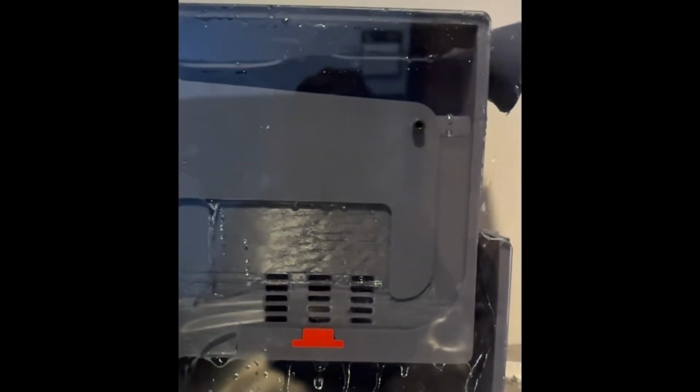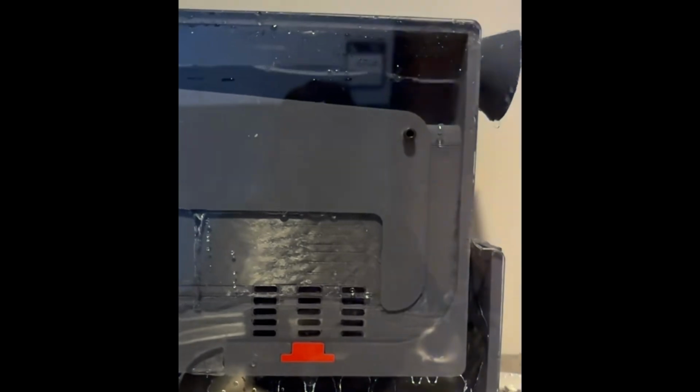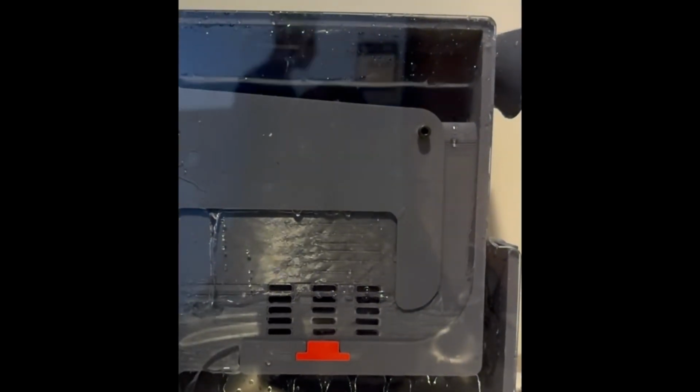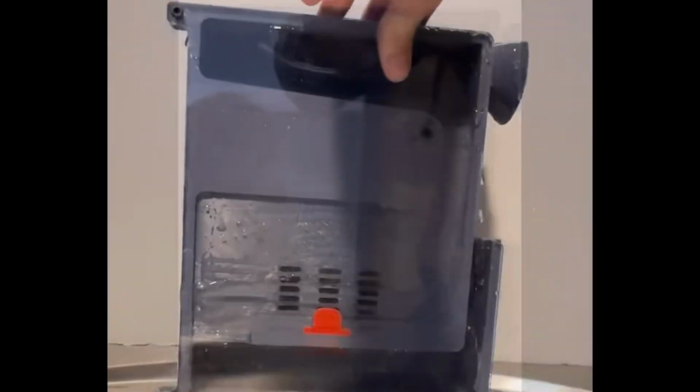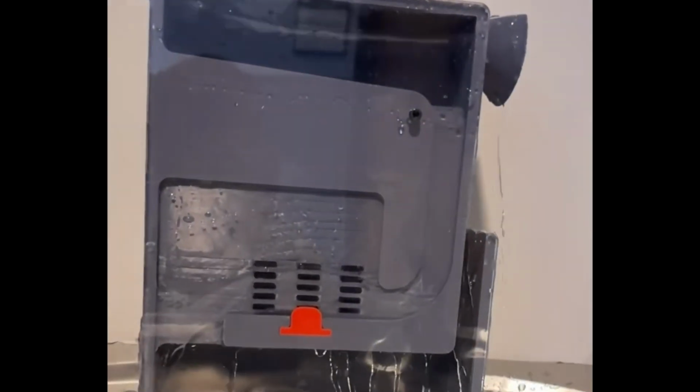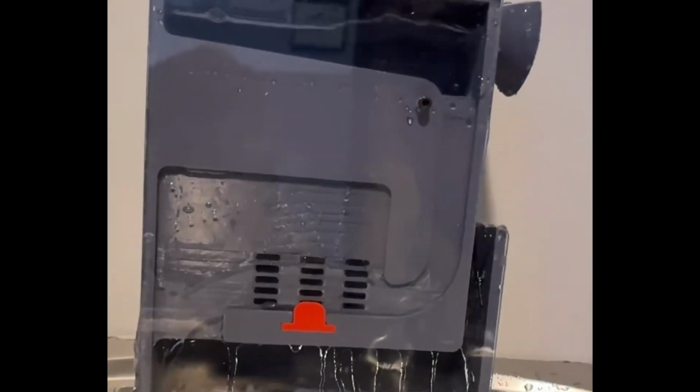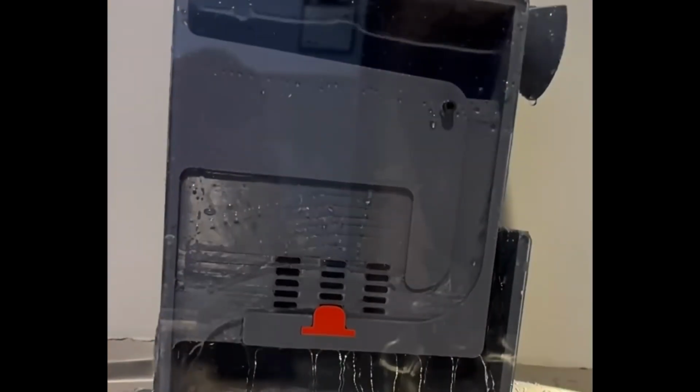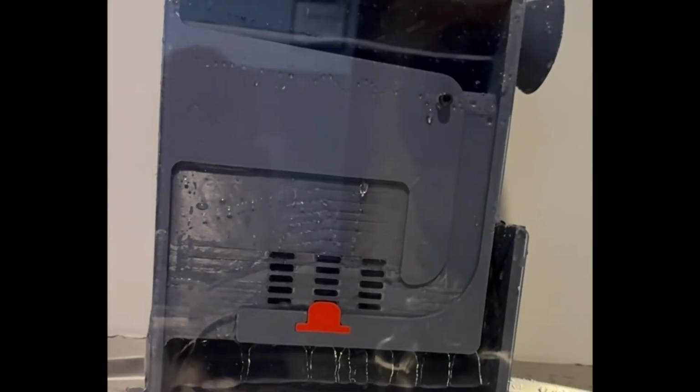Our first experiment was our control volume, where our weir height is 0. Each black mark that you see and the space between those marks are 1/8 of an inch. The height of the water when undisturbed in our experiment was found to be 1 inch. Our second experiment consisted of a broad-crested weir. A broad-crested weir consists of rounded edges, which tends to be used in irrigation and drainage systems. Our experiment consisted of a weir height of 1/4 of an inch, which led to a displacement of 1/8 of an inch above our control.